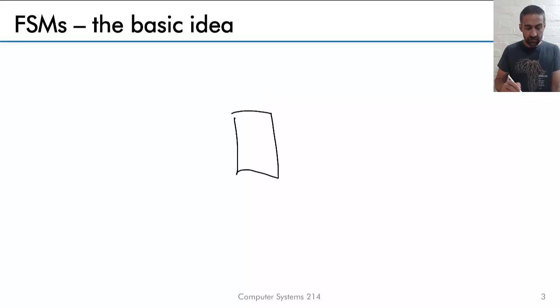This memory module is, I hope you can guess, basically just D flip-flops. They remember the current state, and typically there is quite a large number of flip-flops to remember all the states. So that condition is stored in a flip-flop or a set of flip-flops. All right, so this is the thing that remembers our state. This is the state memory.